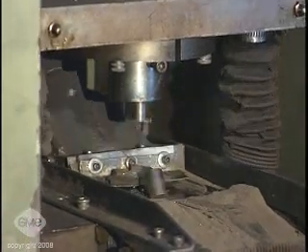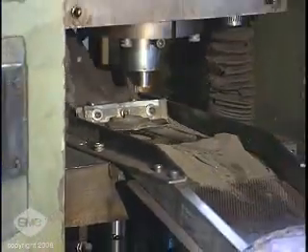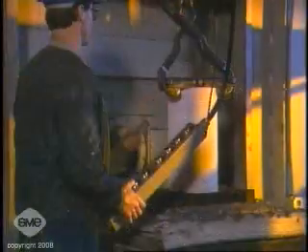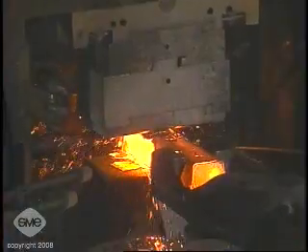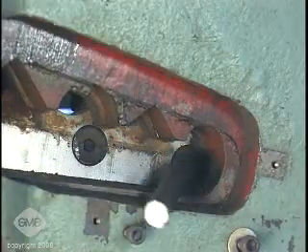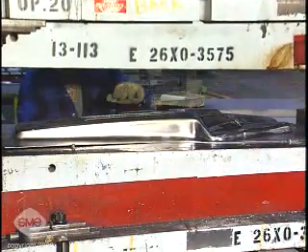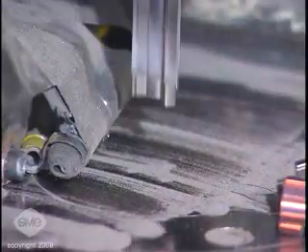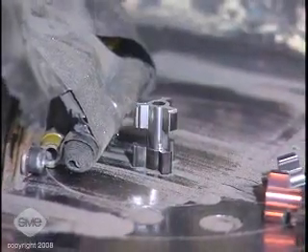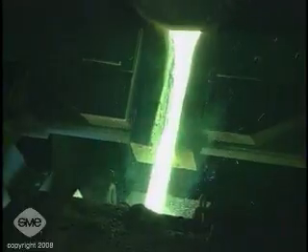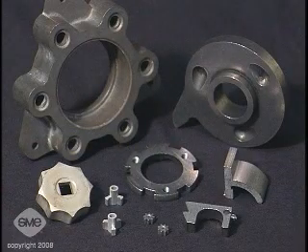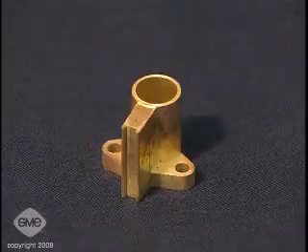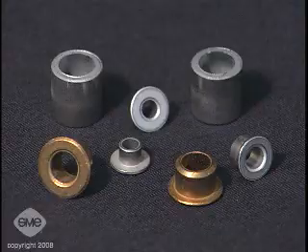Powder metallurgy is a metalworking technology used primarily for producing parts from metal powder. Powder metallurgy is also used to make ingot and billet for subsequent reduction into bar, plate, sheet, and other metal forms. Powder metallurgy dates back thousands of years and is a viable alternative to the use of cast and wrought metals. It is widely used to make a great variety of parts, such as gears, cams, casings, bushings, and fasteners.